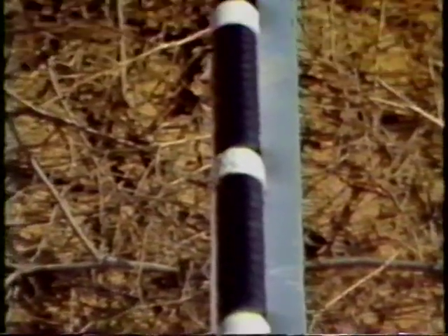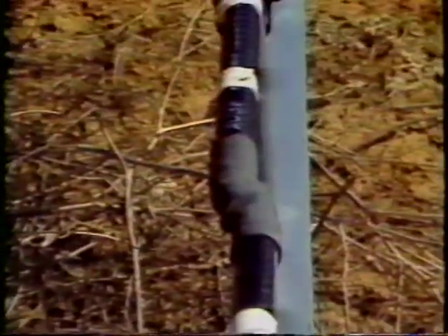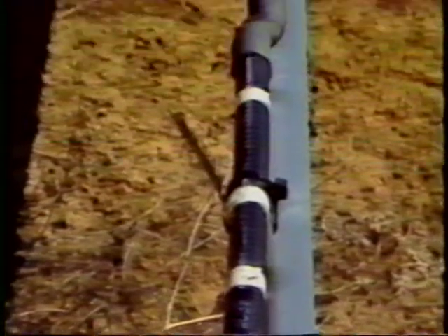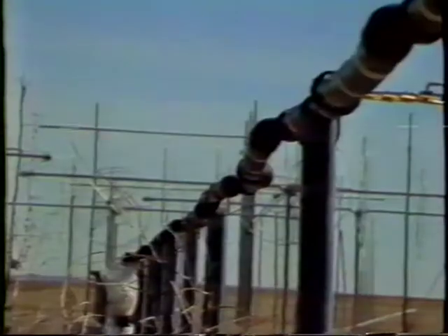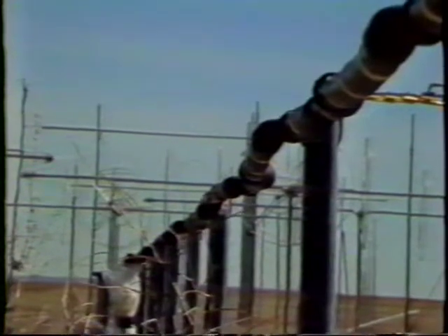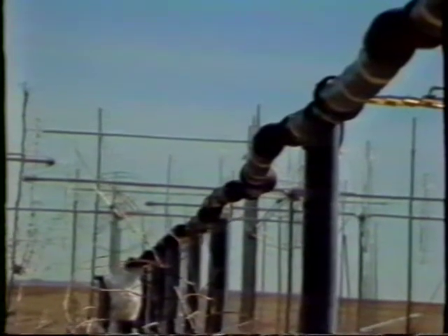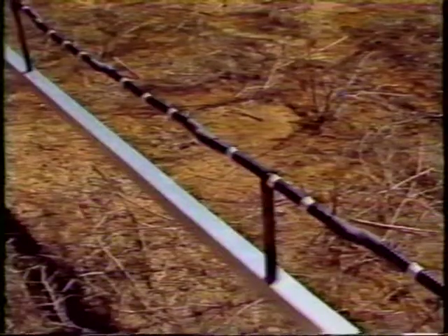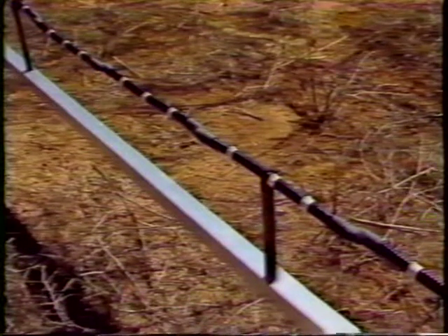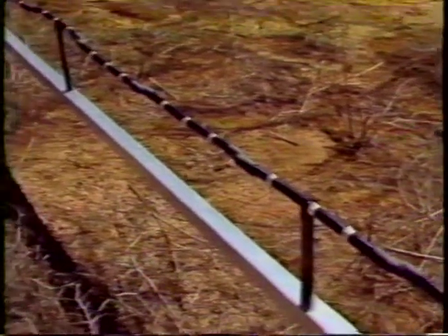Note that the cable is not continuous. Every half wavelength, every 37 centimeters, the inner and outer conductors are interchanged. Because of this spacing, the current in all segments between interchanges is in phase, and the cable acts as a row of half wavelength elements, all radiating in phase.